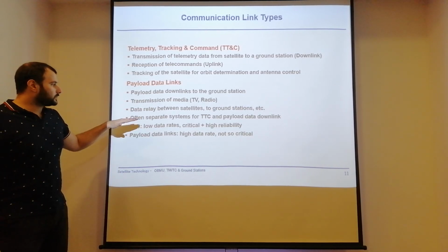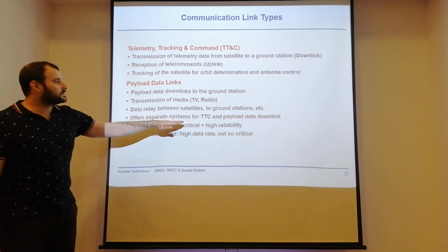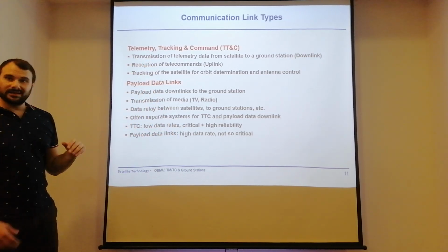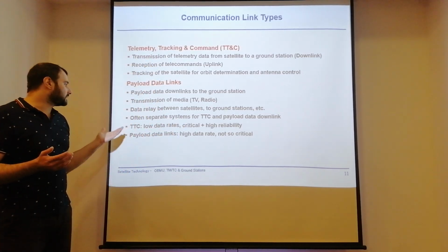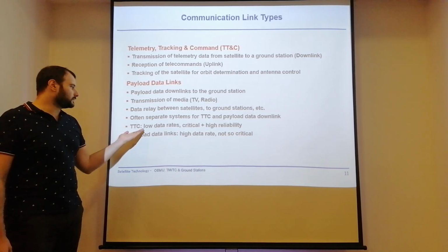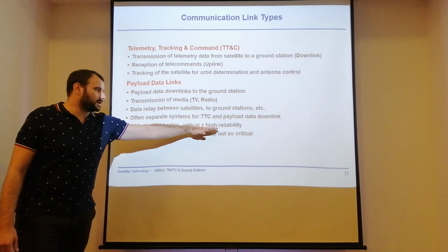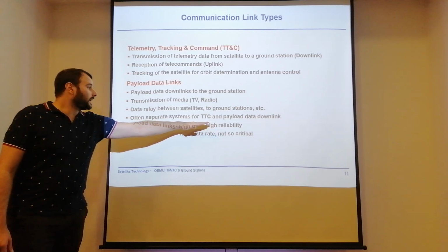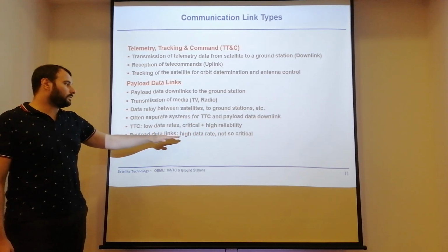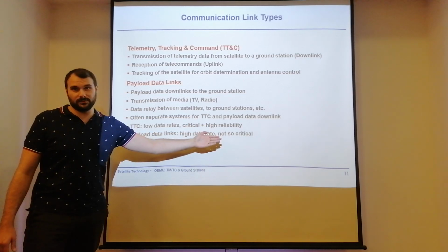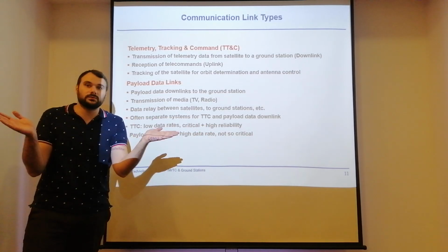And as I said, pretty often the systems for TTC and payload are separated. That just comes from the fact that the TTC only offers usually low data rates, but is very critical and therefore has a high reliability. Whereas the payload data link offers a high data rate, but is not so critical. And that's why you might want to split it into two separate links.